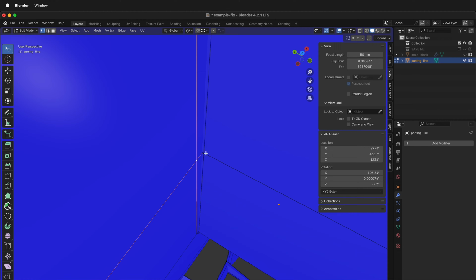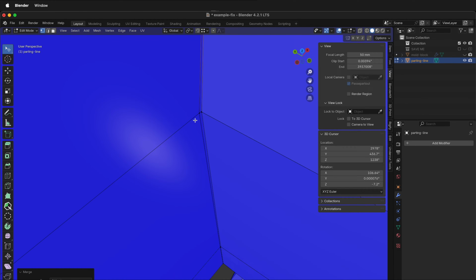Back out a little bit. Remember, this is the corner. Select this vertex, hold Shift, this vertex, M, L, hand down, select this vertex, then this one, M, L.